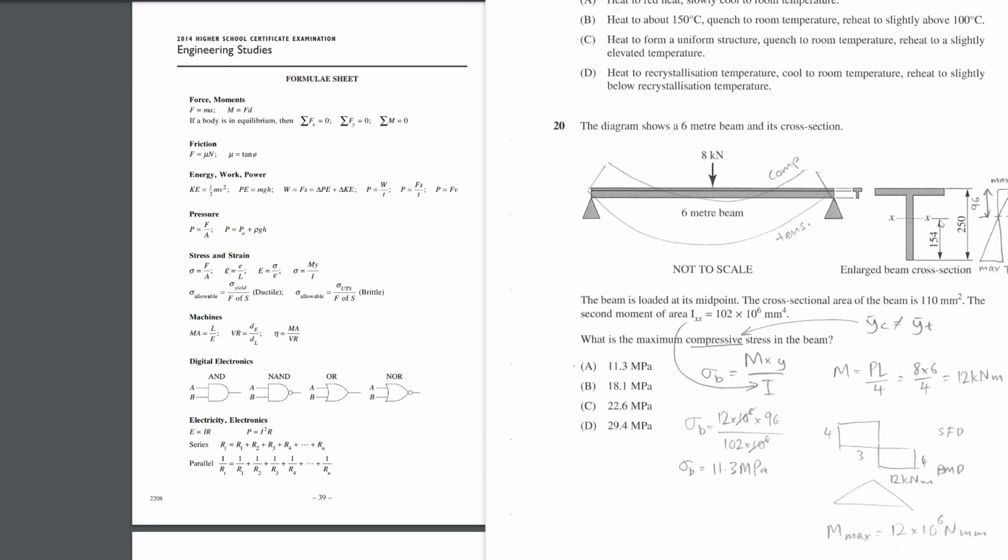Okay, well, we know what the neutral axis is, and we know what distances are, but we have this concept of the extreme fiber, right? So the idea is that these atoms are under more compression. They're under the most compression in this beam. And these atoms are under the most tension in this beam. And this stuff here is under less and less until it's at nothing, right? There's no stress at this point, and then it starts adding compression.